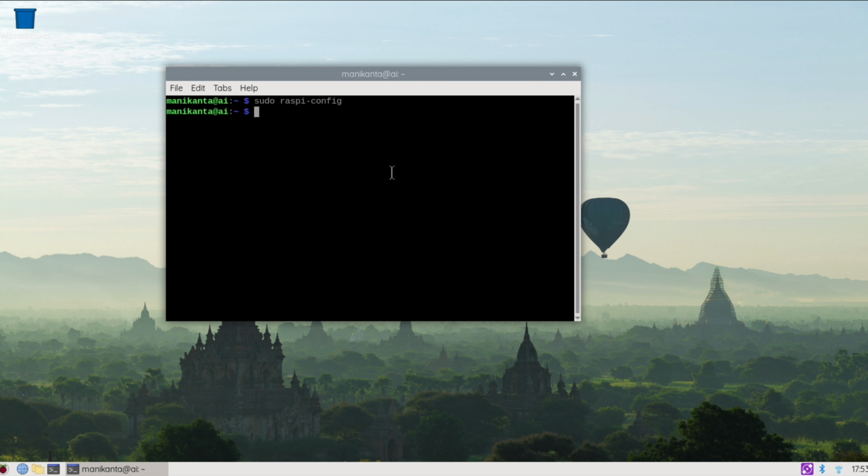And of course, Raspberry Pi 5 doesn't allow you to edit your config.txt directly. What you will do is edit firmware config.txt. This is the newer thing which you can edit. They are storing a separate file in a separate directory, so you can go there and change it from there. And now your second process is also done.